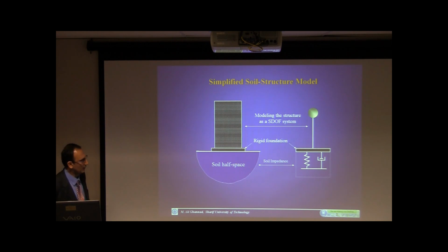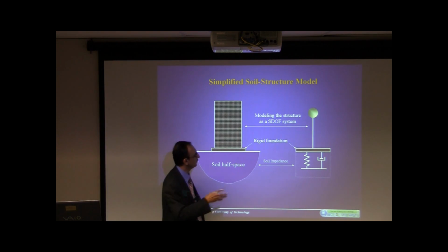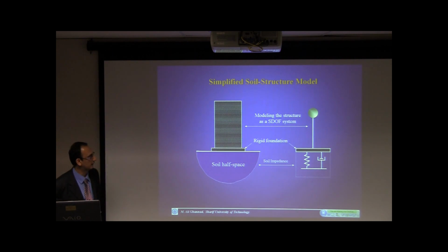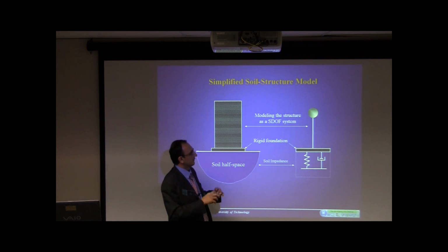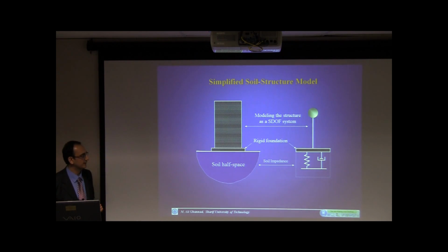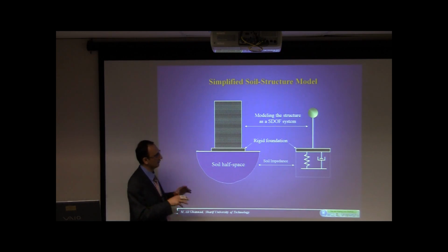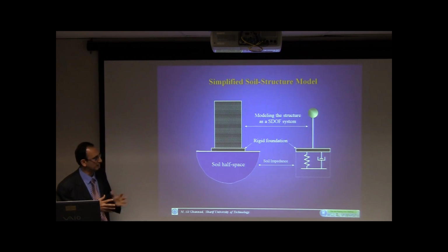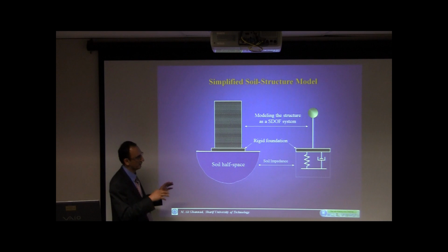This is the simplest model that you can imagine, using a single degree of freedom model for the superstructure and a rigid foundation. Of course, we know that the foundation is not rigid, but considering the flexibility makes the problem very complicated. In the simplified methods, it's customary to consider the foundation rigid. And this is the concept behind the current regulations, which use almost the same method.